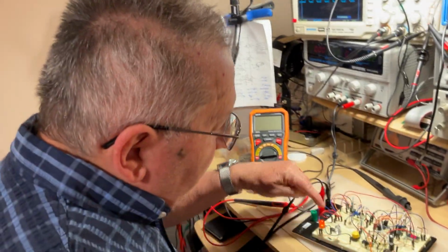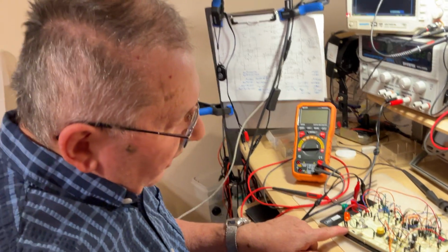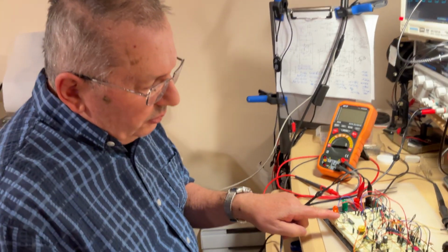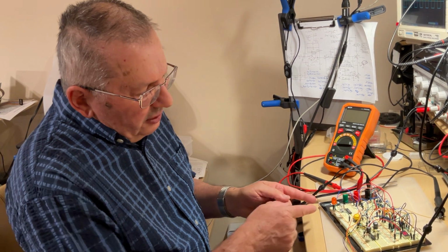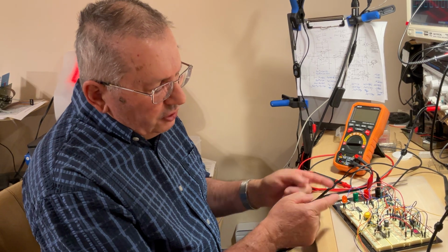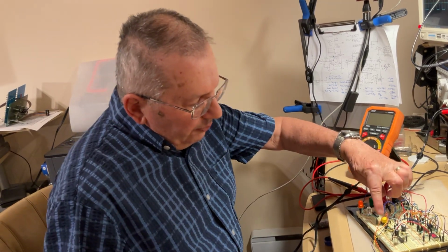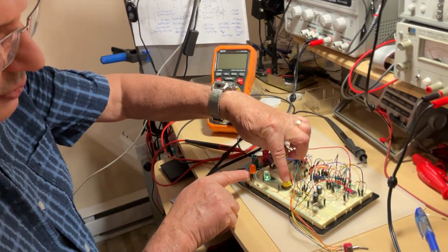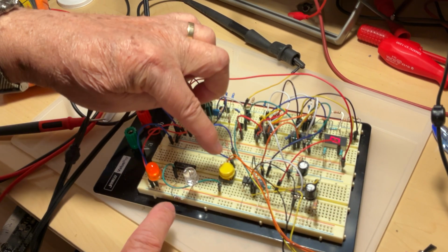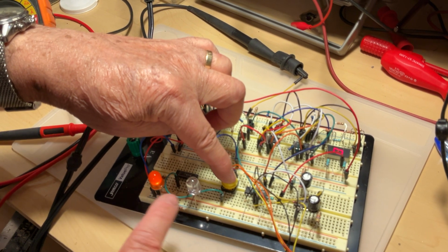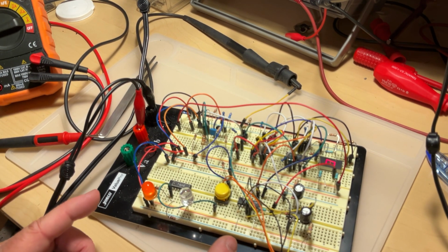Right here, I have a package containing inverters already connected. And this LED here on my left, the orange one, is connected over the input, and the other one, the green one, is connected to the output. So as you can see, when one is on, the other one is off. This is why it's called an inverter, because the input and output are opposite to each other. When I press that button here, the input goes 0 and the output goes 1. So 1 meaning it is on, okay? Input 1, output 0, or input 0, output 1. They are always opposite to each other.